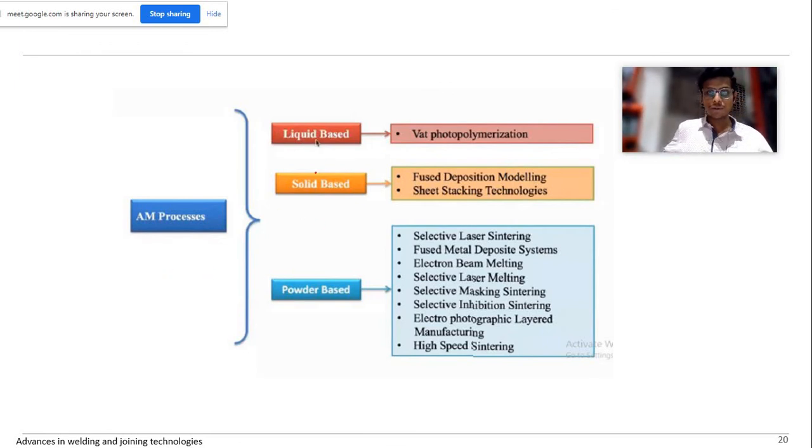And I don't know, if you guys did any course about this, it will be easy to understand. So in the question, we are using a laser power source, right? Yeah, because in this you can see selective laser sintering, even selective laser melting, and other things also. We use laser as a power source to melt the powder material to generate the required component based on the CAD model. And also we can use electron beam welding.